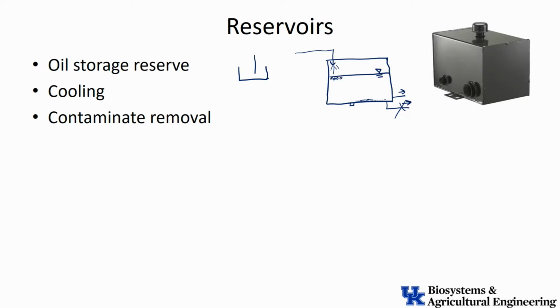Air bubbles are a really bad thing for fluid power systems. If they don't pop and dissipate, which if I have a fairly viscous fluid, they're going to stay in that fluid for a while, and they could actually be carried right down here to the intake. And now I carry these air bubbles into the pump. When they get into the pump and get subjected to the high pressure on the pressure side of the pump, they will collapse. And when those things collapse, they create a large force and they can actually pit the metallic surfaces of the pump, so they can damage the pump. So air bubbles are a really, really bad thing.